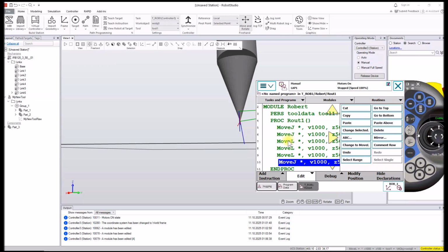And this is a short movement which the tool will touch the table, and from this point to this point the robot will do single line, short line. Here moves up from this point to executing this line, moves up. This is linear motion, because here we need to control the trajectory. This must be linear motion when we remove the tool from the object.